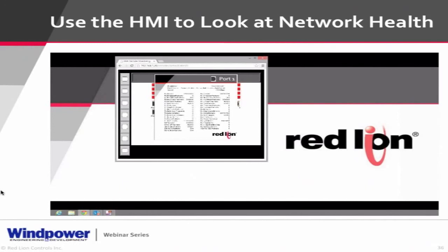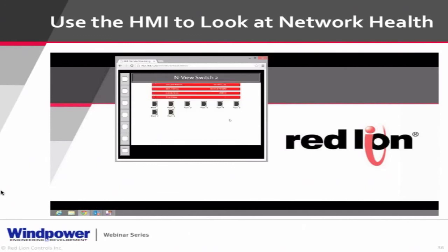Now, one of the benefits of the DSP that you guys would be interested in is as you retrofit these towers, you'll be pulling some equipment out and putting new equipment in. So you may have a PLC from one manufacturer talking to a PLC of another manufacturer, but these PLC manufacturers may not all have the same protocol installed or work talking together. The DSP will actually do protocol conversion, so it'll talk from one protocol language to another for you, so it acts in the middle. So you don't have to just pull everything out of the tower. You can do it in a phased process instead of doing it all at once.